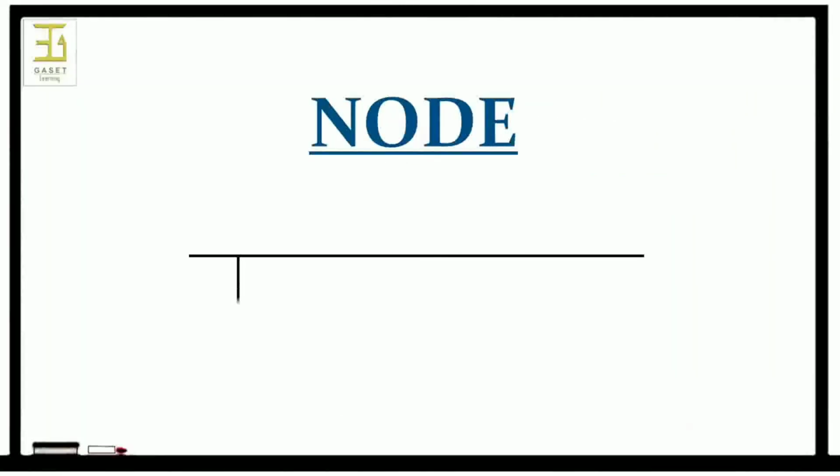What is a node? A node is anything that has the same potential that's connected electrically together. So every point on here is the same node. Now I might have a different current going through these branches having this node, but the voltage everywhere on this node is the same with respect to the ground.